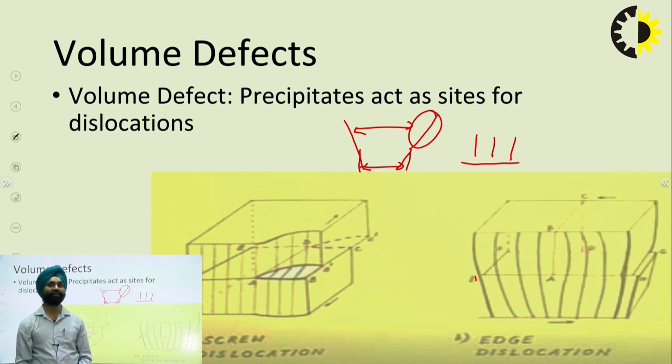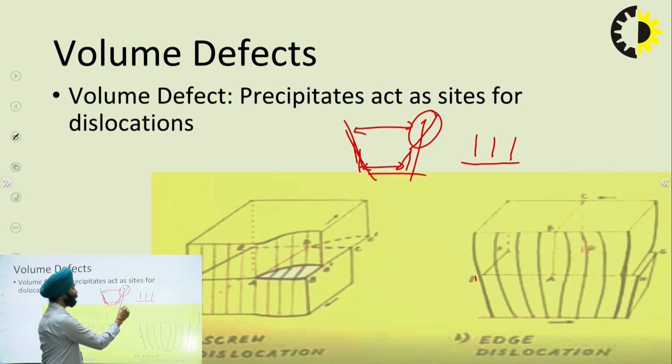Now again, we can see all the problems of ingot preparation, as well as for the doping of the ingot or the wafer. Here the density is changing, so the doping will not be the same. Also, the crystal orientation will be different, so all the properties of the wafer will be different. So if we have an ingot with this structure, the conductivity of the lattice will be different.